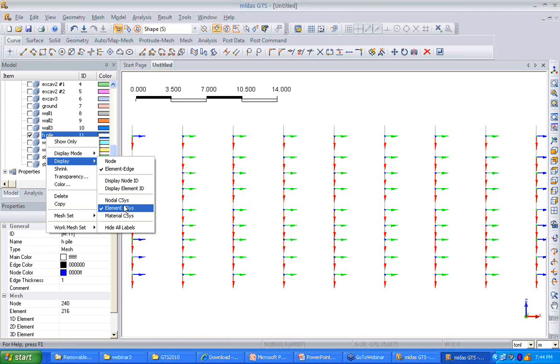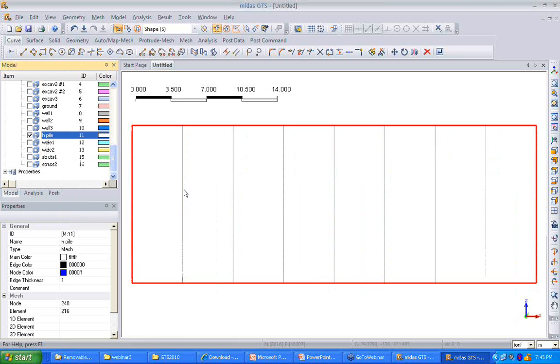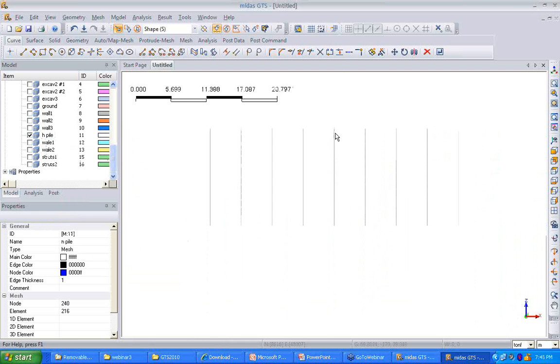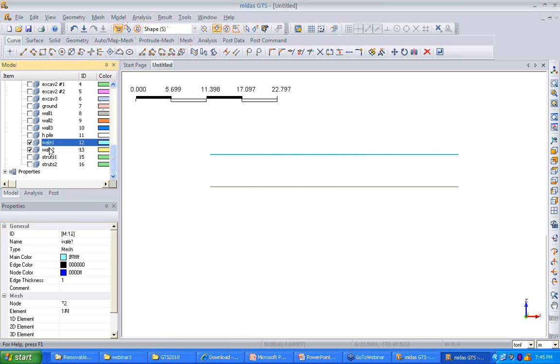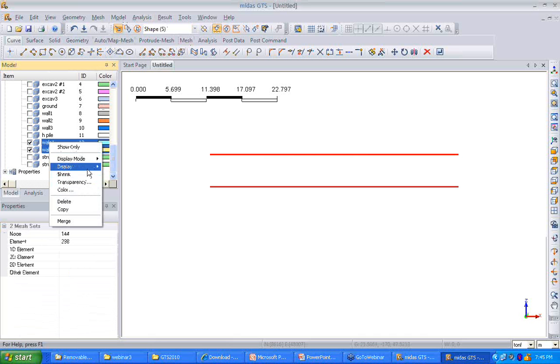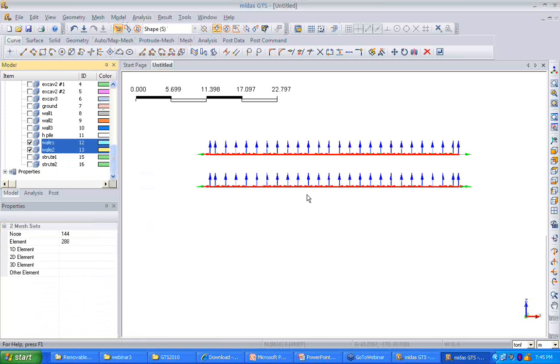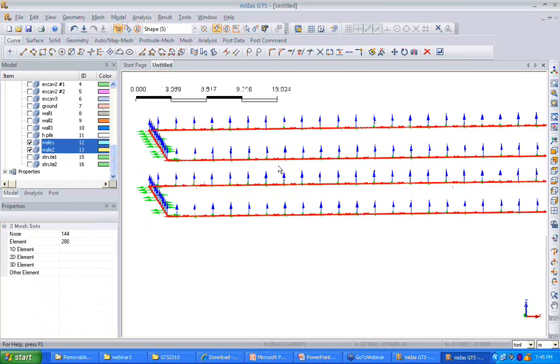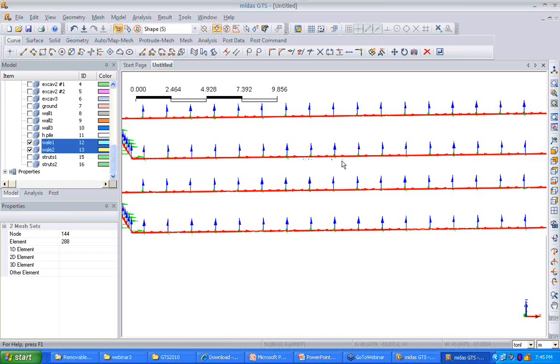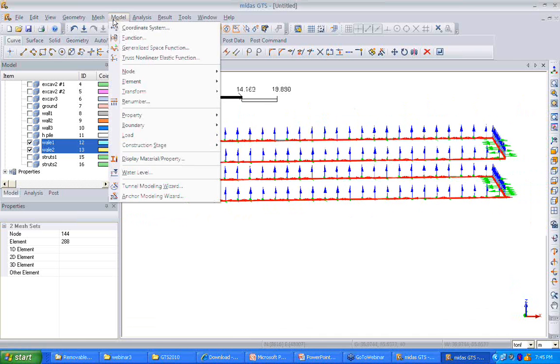This is a very important concept when we need to realign all our 1D elements in a particular direction so that the element forces don't cancel each other. Similarly, the same is the case with the walls. The local x forces are cancelling each other, so again we need to align these things in a particular direction.